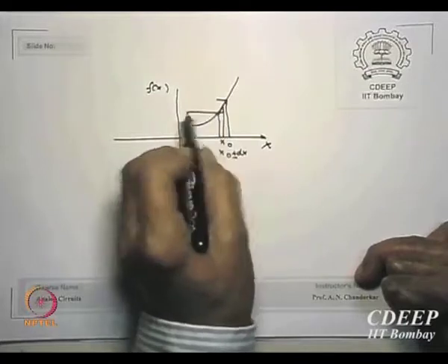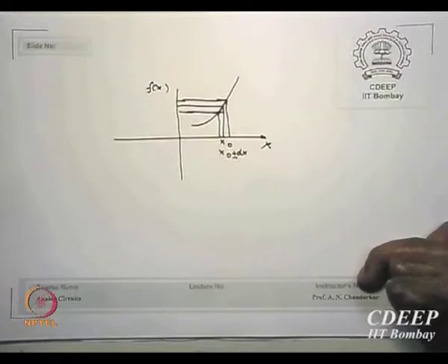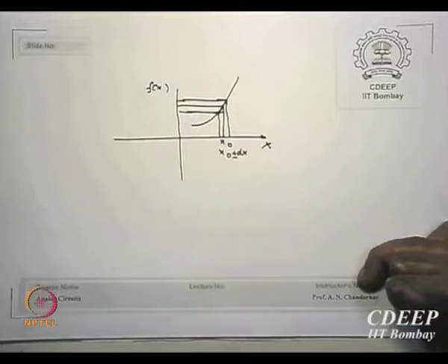I would say the output will be proportionately linear at these points, exactly linear, therefore proportional. Equivalently, x0 is your DC value and plus or minus dx is the AC signal. So the AC signal does not change the VGS minus VT. Currents are essentially DC current, proportional to VGS minus VT, around which the AC signal just superimposes. Therefore, it does not change the status of the transistor just because a small signal is superimposed on that.